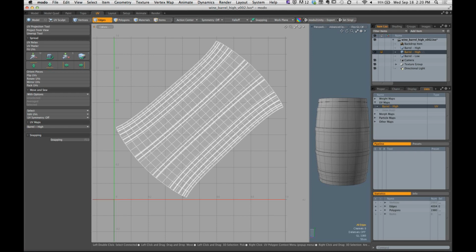Now, Waddell, I like what you have going on here. You're getting some really good edge selections. However, keep going with your iterations. Yeah, keep left clicking and dragging. You're only at 325 iterations. It flattens out. Interesting. Okay, do me a favor. Zoom out a little bit here, Waddell. Drop your tool and hit undo. Let's get rid of that UV. There we go. Drop your tool again so we don't accidentally reapply it. And let's just take a look at what you got going on.